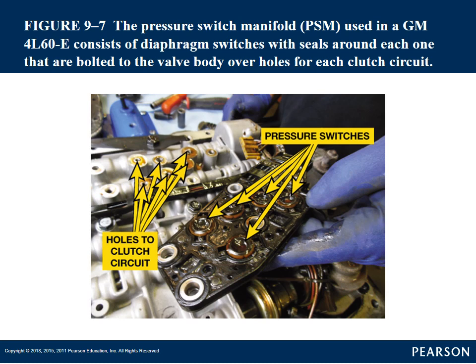In this switch assembly, it has the temperature sensor. It's near the front there, but you can't really see it because it's so dirty. And that could cause a malfunctioning temperature sensor reading also when they get this dirty.